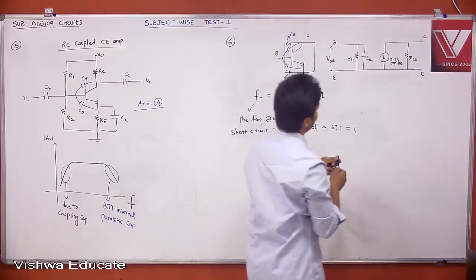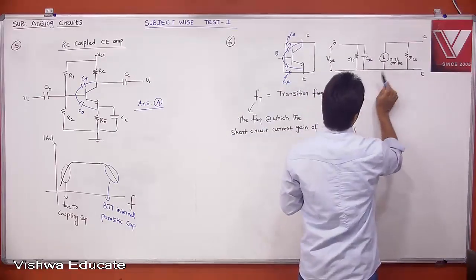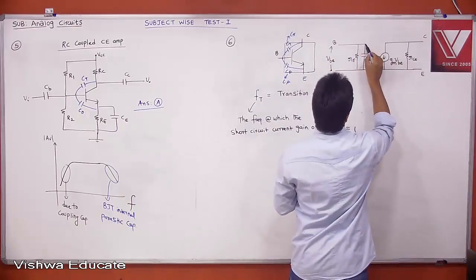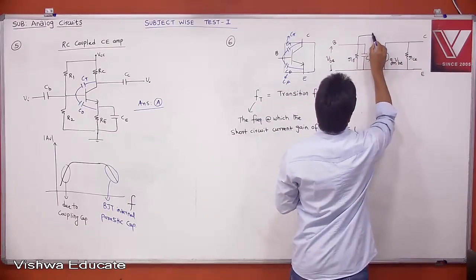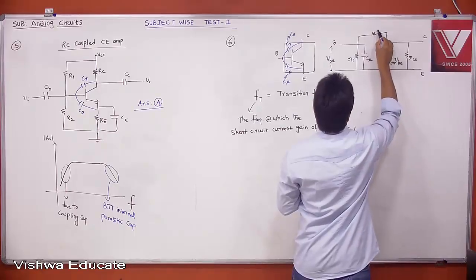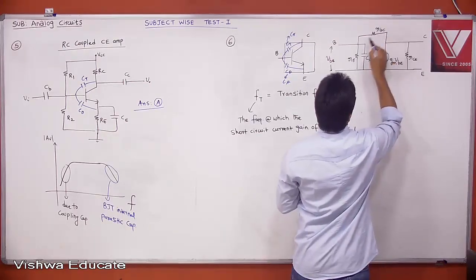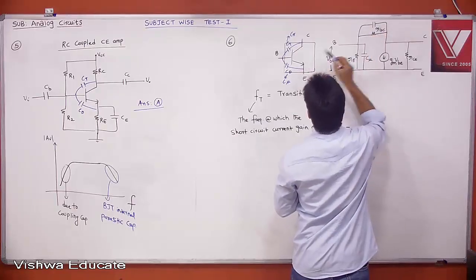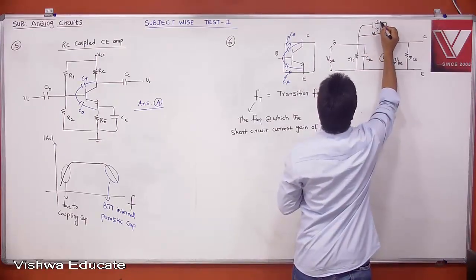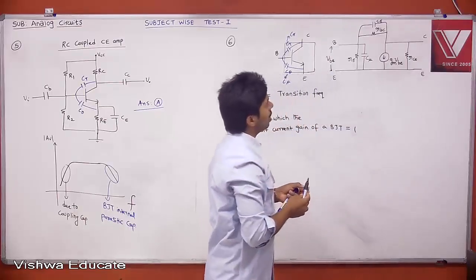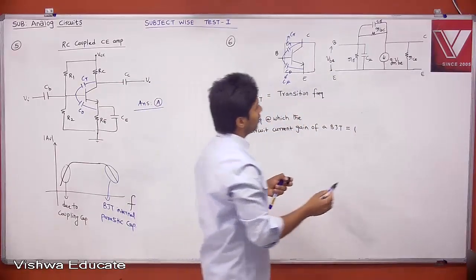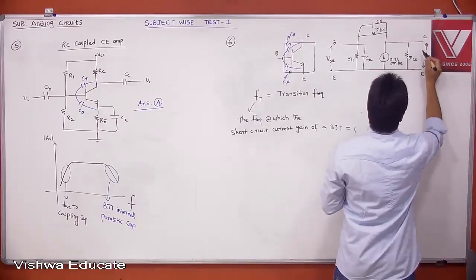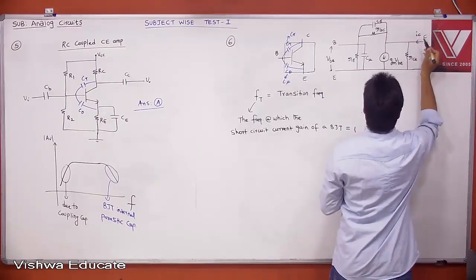People also represent some resistance, right? That is to have feedback from VCE to IB. Therefore, this is what people added. This is RBC, because of base width modulation, and there is a cap. This is our C pi. And this is your VCE, and this is your collector current, small IC, and this is your base current, small IB.